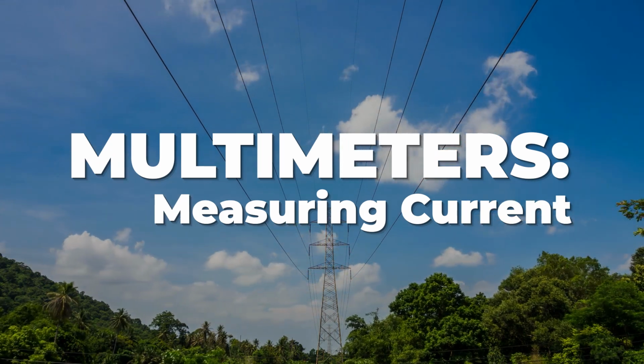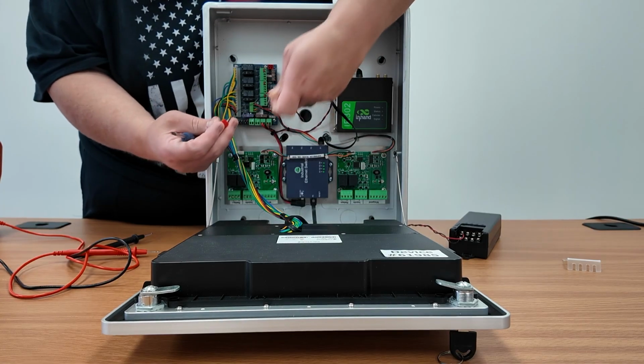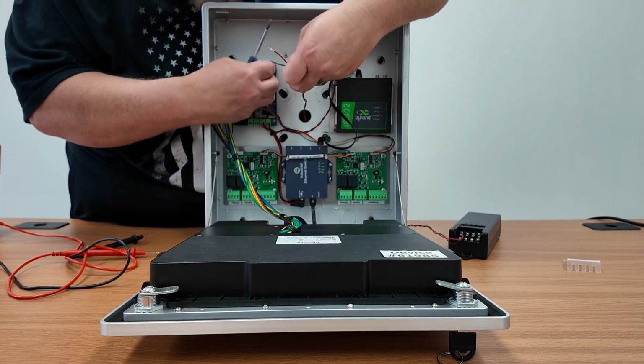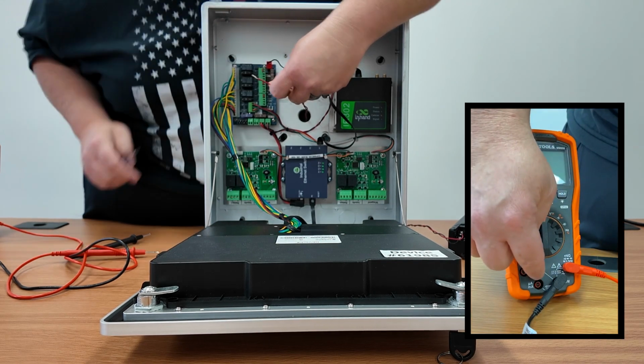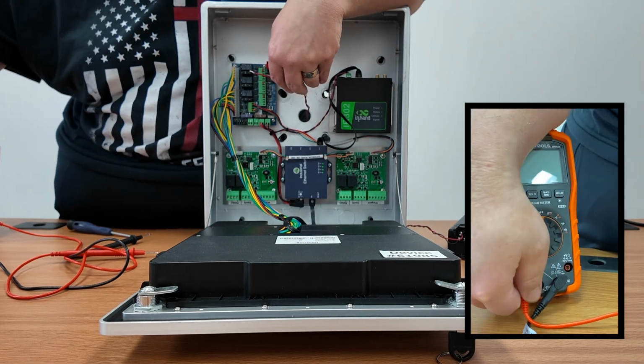Measuring current or amperage. Current is the rate of flow of electric charge. To measure current accurately, you must disconnect the power source and the circuit you're testing. Ensure the multimeter is set to the appropriate current measurement range by selecting the correct current jack. This is crucial to prevent damage.